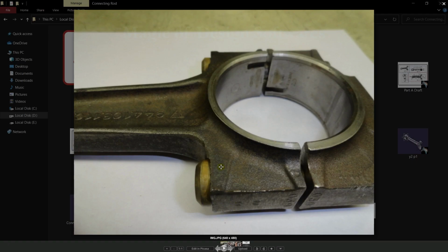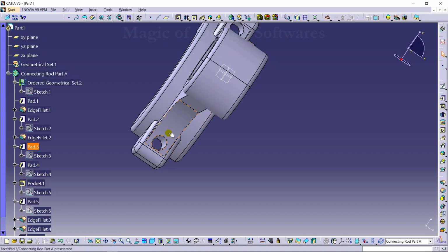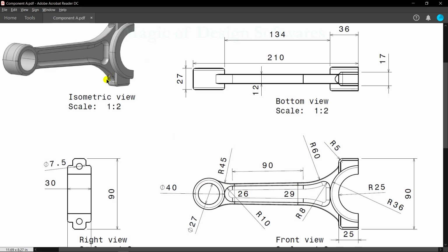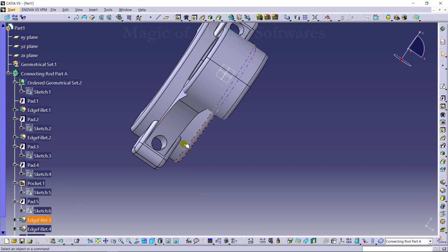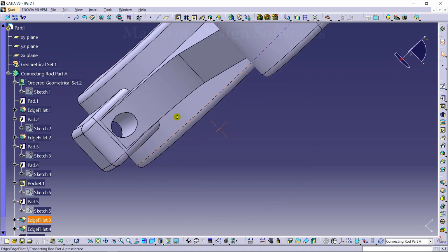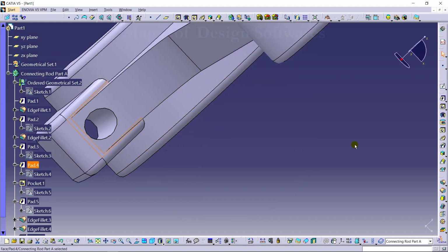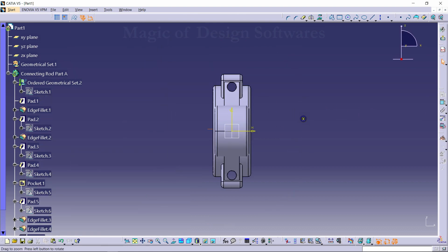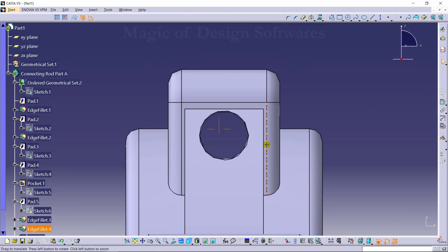so now for making a cavity over here to insert a bolt head easily, so I'm just making a cavity at this place like this. So now I'm just selecting the surface of this, sketching it, and making it as an offset.